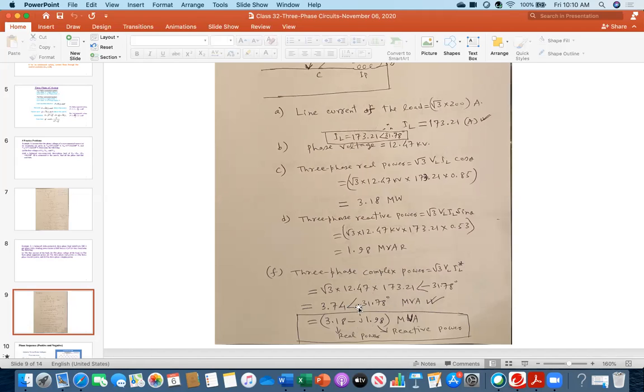And then after that, just in 30 seconds, I will release you. I converted from polar form to rectangular form, and then I got this result, this minus this. The first part represents the real power and the second part represents the reactive power. And really, you see it matches what I calculated in part C. I got the minus sign.